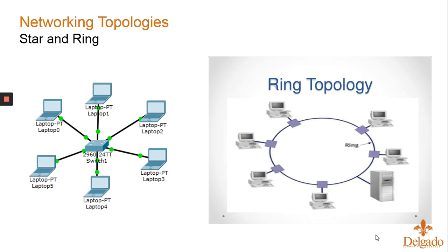We could do a daisy chain approach from device to device to device, assuming that each device has two ports. And for the trunk line, there is an older precedent on Ethernet to use coax, and you could create that trunk and tap off the trunks. But in most modern topologies that we see on the plant floor, it typically boils down to either a star topology or a ring topology. So those two examples are shown right here on the slide.